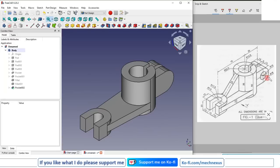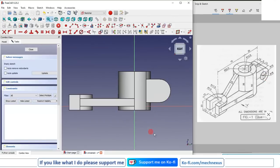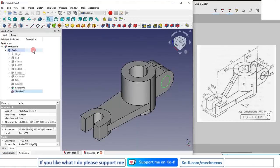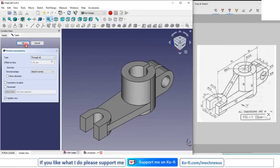Now we will make this hole, so I will select the face and create a sketch, and I will project the geometry so we get a center point. Now I will select the circle and draw the circle. You can make it with the hole feature of FreeCAD, or you can make it as a cut. It is up to you. I will select the diameter and I will give here 16 and I will close it and I will go with a cut, and here I will say through all and say OK.